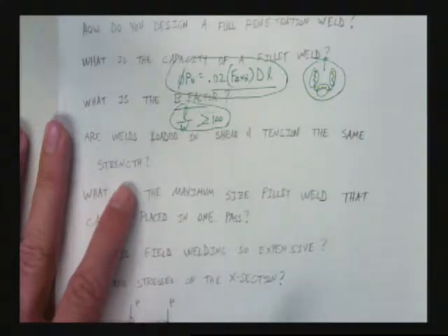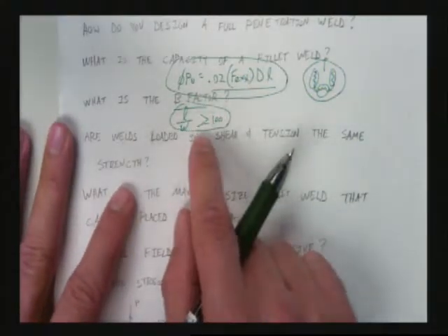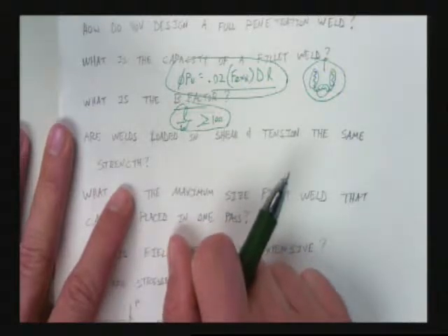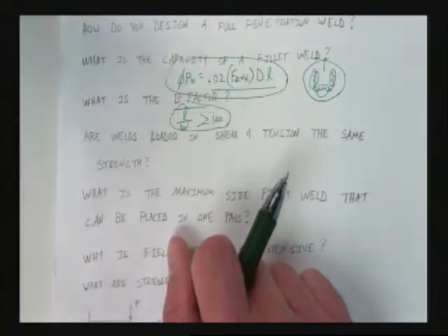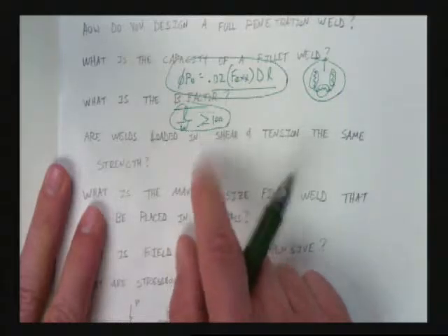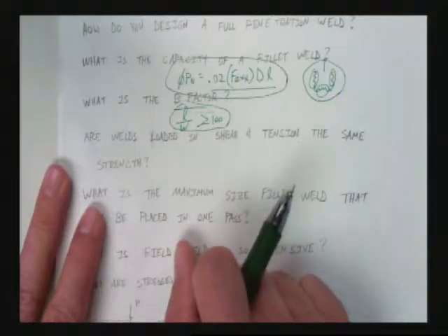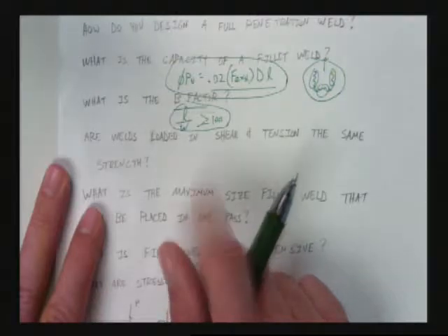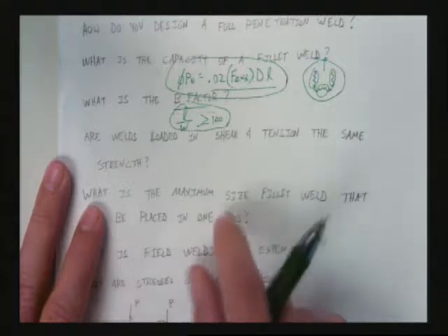Now, why do we have it? Why do we fear long welds? It's very challenging to place a long weld without making imperfections in that weld. Extremely challenging. It sometimes gets hard to catch imperfections in really long welds.